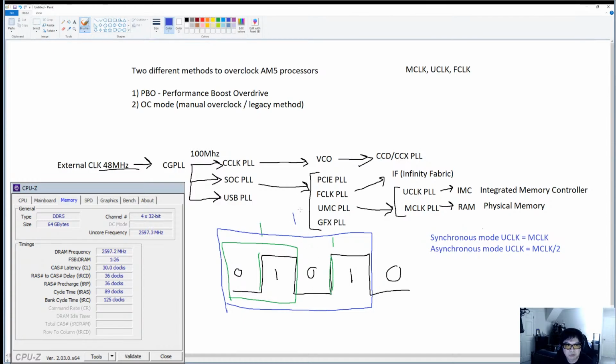So this 1 command could be on the falling edge. It'll probably be on the falling edge of the first clock cycle, or however it does it. I don't know the full details of how it actually sends that command, but effectively you get 1 command every other clock cycle. So if this executes on the first clock cycle, the second clock cycle won't have anything sent down there.